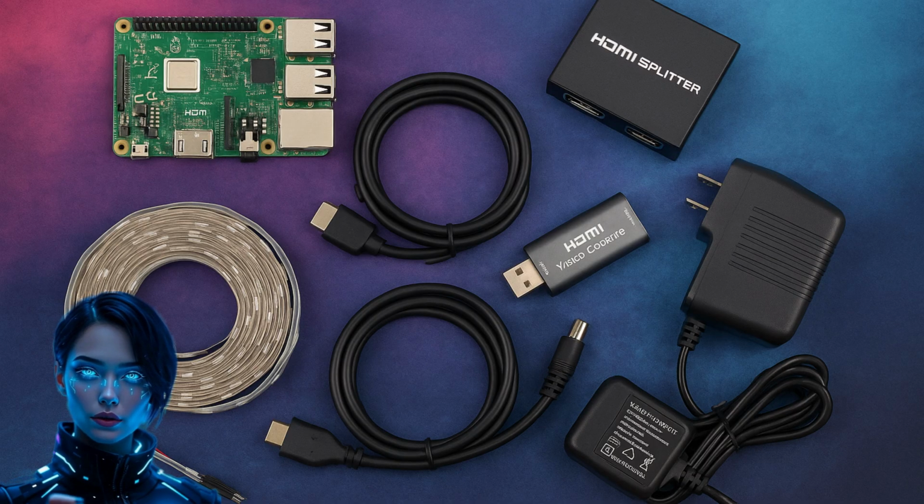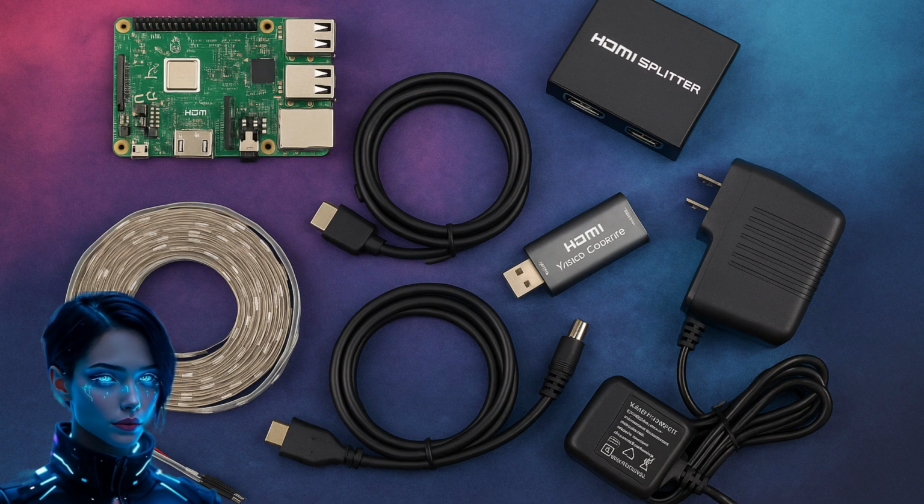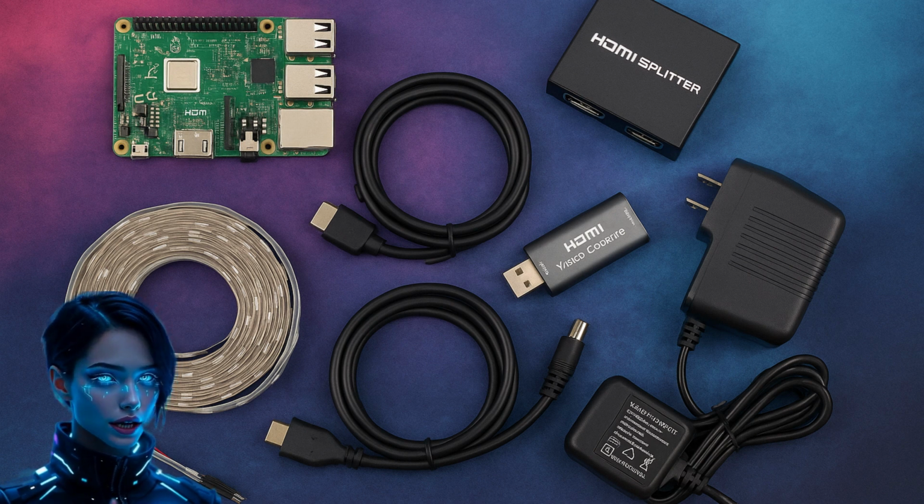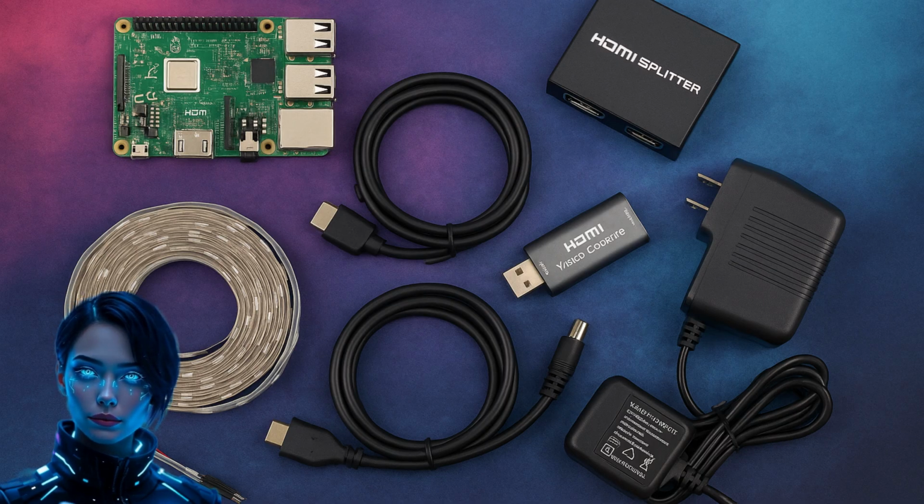To build our Hyperion system, we only need a few components chosen carefully. First of all, let me highlight an important point. Hyperion cannot work with images played directly by the TV. You'll need an external video source, such as a TV box, a Sky device, an Xbox or PlayStation console, any device that sends both audio and video signals. Only then can Hyperion capture the colors from the video and synchronize the LEDs in real time.